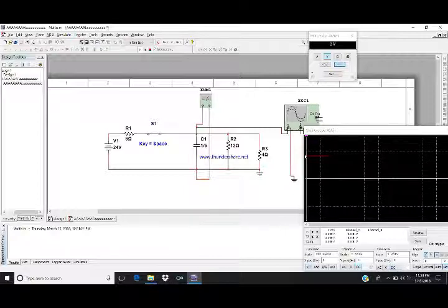Okay, here we can see the voltage at the oscilloscope and voltmeter are the same and stop at 8 volts. So the capacitor is now fully charged and we will open the switch to discharge the capacitor and see the graph. The graph will continuously decline, which means the capacitor is discharging. At this condition, the capacitor provides the voltage to the circuit until it is fully discharged.